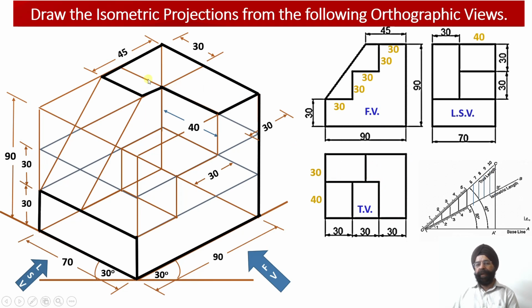So this we have been able to obtain, and then these are the slant edges corresponding to the inclined surface. So this slant we are able to see over here. In the front view, this is the slant web which we are able to get, and in the side view also we can check, this is the rectangular surface which is the apparent view of this inclined web. This inclined web is having bigger size, while in the orthographic projections this larger surface of the web appears to be an apparent shape in the left hand side view.